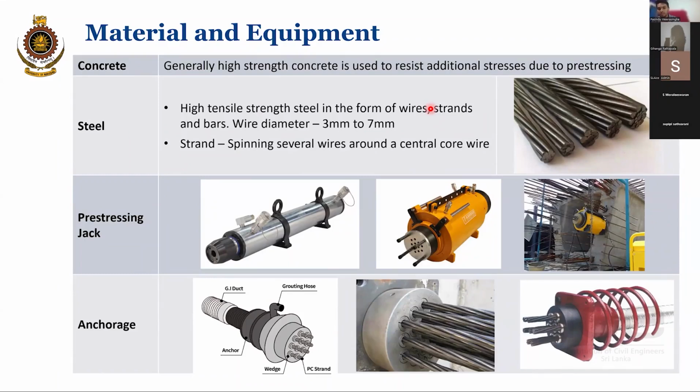In terms of girders, it depends on the size of the member that you require, and also some practical considerations. Like, if the pre-stressing yard is very far away, rather than spending cost on transportation, you can do the post-tensioning on the site itself.